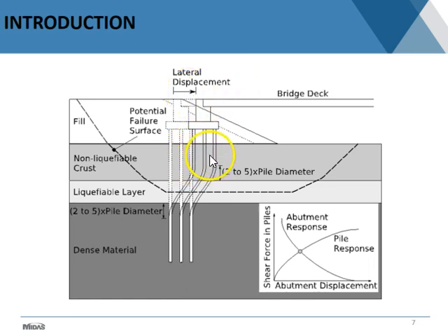When you deform the piles this way, the piles try to go back to the left, so they try to restrain the movement. This is what is called the pile pinning effect, because the piles pin the upper structure in the dense layer here at the very bottom. Okay, so you need long piles embedded in good soils to have this kind of effect.